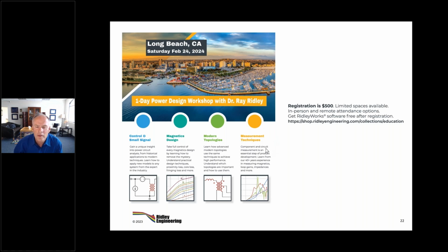Do we use the frequency components of the current waveforms versus RAC? Yeah, LTspice does that naturally. You put in RAC as the LTspice model, and it naturally is decomposing into all the harmonics, multiplying I squared R for all of those, and finding the solution. That's the beauty of these LTspice models that you build. You can't do that analytically. You can't extract all those harmonics easily and then multiply every RAC, which is the solution to Dowell's equations, or in our case, of course, it's measurements. So there you go.